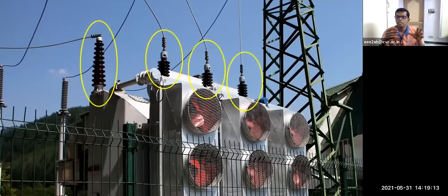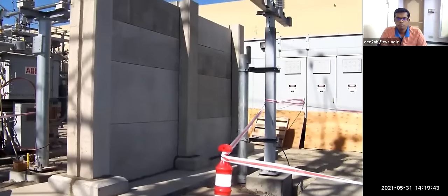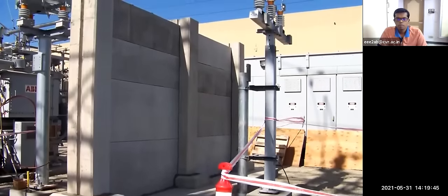So wherever it is necessary, they will install oil cooled current transformer, oil cooled potential transformer, oil cooled circuit breaker or vacuum circuit breaker. Then your transformer is also oil cooled plus air cooled. Like that, wherever necessary, they may install these fans also. A device called a bushing maintains a safe distance between energized lines and the grounded metal housings. Some substations have large concrete walls to serve as fire barriers between equipment.